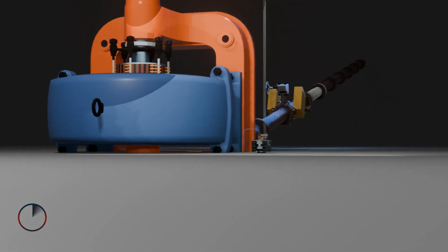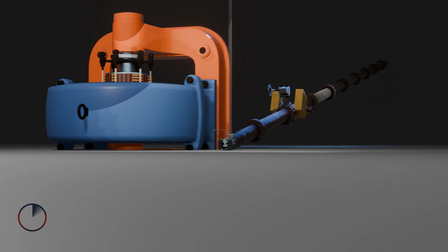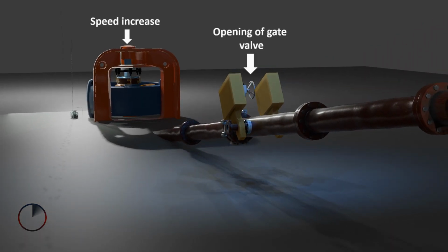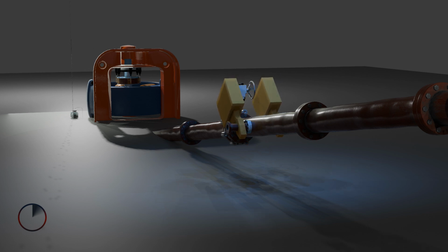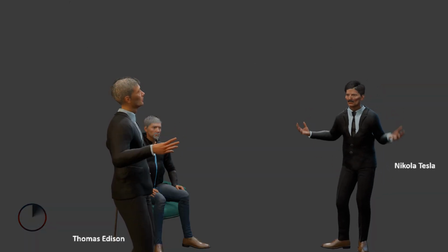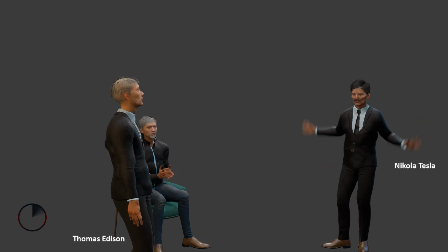So in a nutshell, before synchronizing the generator with the grid of other generators, the AC generator must additionally match in its timing. This is the timing of the frequency and the voltage rating of the network being synchronized too. This requires both the speed and the excitation to be systematically controlled for synchronization. This extra complexity was one of the arguments against AC operation during the War of Currents in the 1880s.